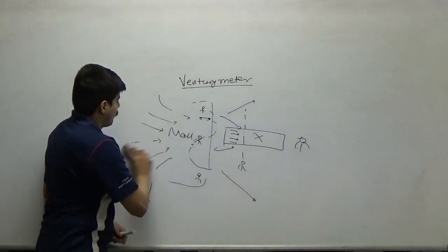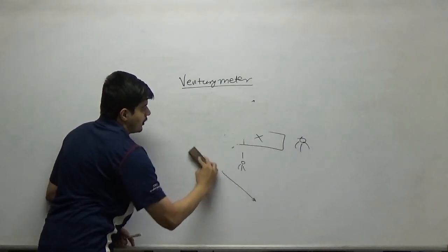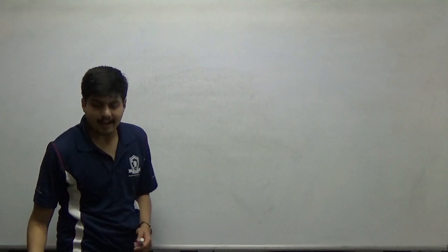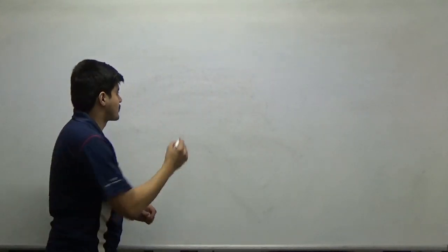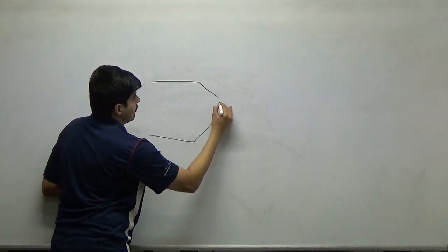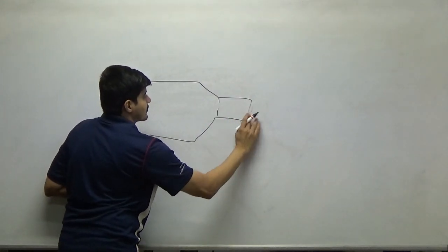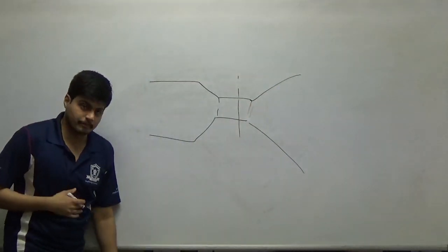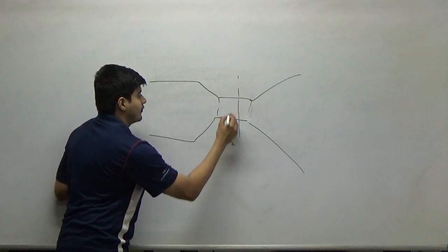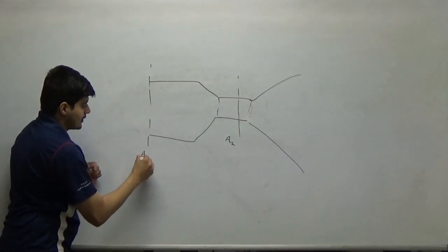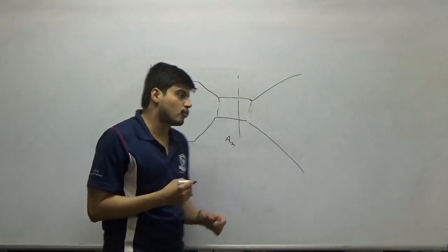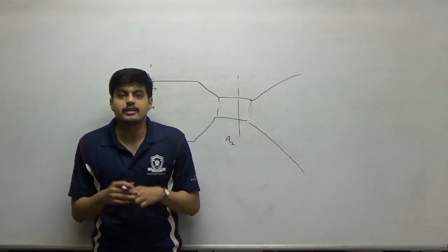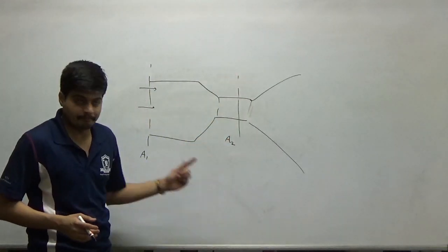So very simply, what you have done is you have made the flow get confined in a constrained area and then used that area for your approximated measurement equations. Therefore, your Venturi is typically denoted something like this. This is that Venturi. This is A2, the area. This is the entrance area, A1. Why did we do it? Because the flow upstream may have certain vorticity, may have certain non-uniform characteristics, non-streamlines. We have got rid of them.